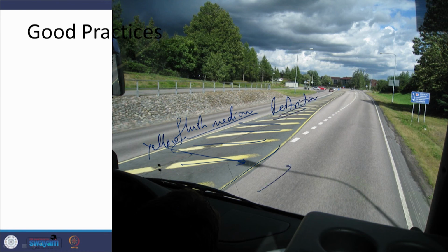So, they have to move either in this direction or in this direction away from it. This is one thing being defined. Then this slope is there. So, it is a recoverable slope. So, because of this recoverable slope, the vehicles can come back in this form. There is another path coming on the other side which is being protected by way of the railings being provided. There is an edge marking and then you have the shoulders on the sides.